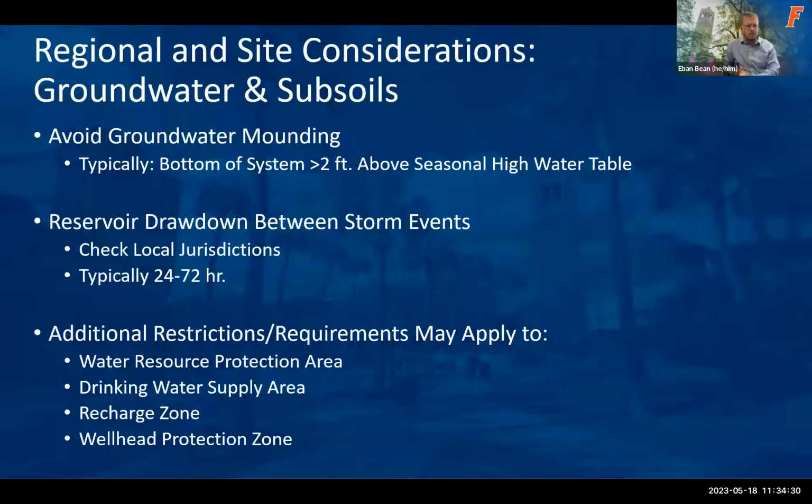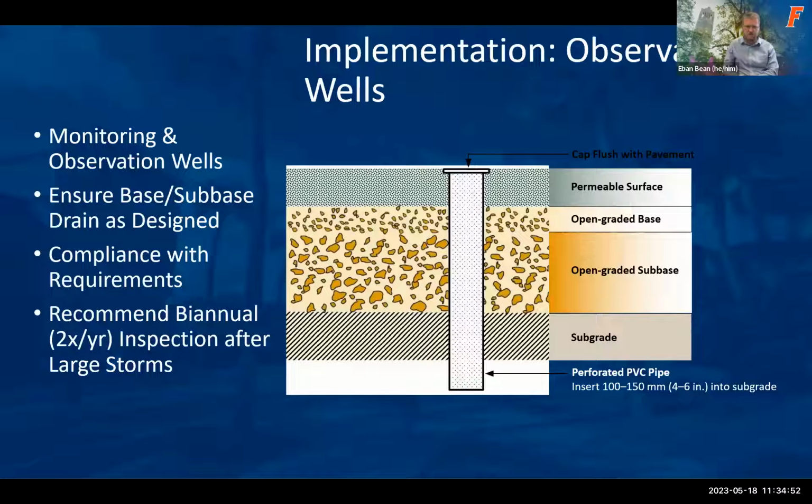Some of the things just to keep in mind for your regional and site considerations when we think about groundwater: again, keeping the bottom of that reservoir at least 2 feet above the water table. We want to make sure that the reservoir can recover its storage typically within 24 to 72 hours. And again, staying away from at-risk areas that may have a contamination risk.